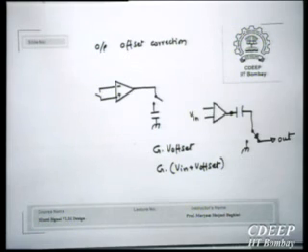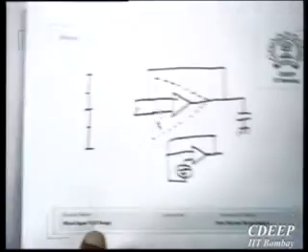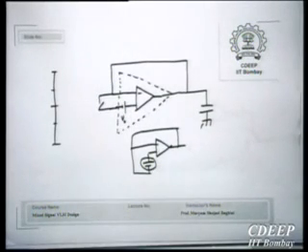Right? I am not shorting the input anymore. So since there is this internal battery in series, when I apply some input, this battery will come in series with that, and therefore the actual voltage seen by the imperfect op amp is the input voltage applied to it plus its offset, right? And that whole thing will be multiplied by its gain G. Okay, now what happens?